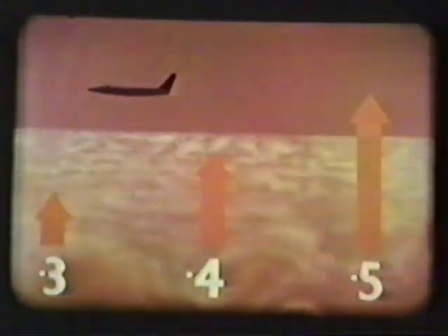The first shock stall trouble is a sharp rise in drag. At speeds below M crit, drag is roughly proportional to the square of the speed. But when shock waves develop, they cause a much greater rise in drag. For the energy dissipated as heat by the shock wave must be continuously supplied by the engine. This causes a new kind of drag, wave drag.